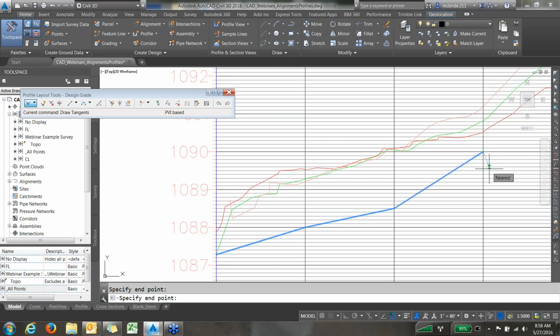The problem is when you're done drawing this grade, right there you have 3 different grade breaks, and that's within 300 feet. And typically when we do grass waterways, we're not going to have that many grade breaks in the design. We want to have as few grade breaks as possible while still having a good design. Now, if that means you have one continuous grade, that's great. It doesn't usually work out that way.